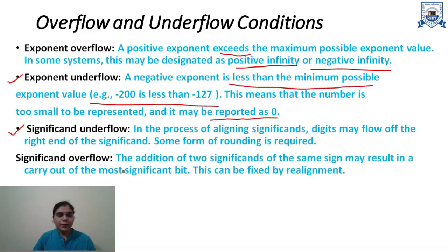Significand overflow. The addition of two significands of the same sign may result in a carry out of the most significant bit. Whenever a carry is produced from the most significant bit of the significand addition result, then significand overflow occurs. And this can be fixed by the realignment of significands.